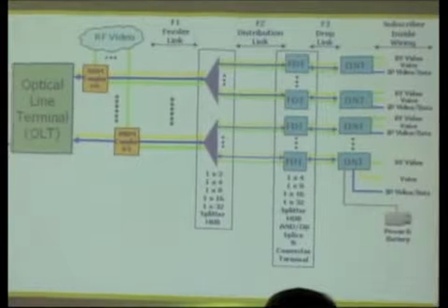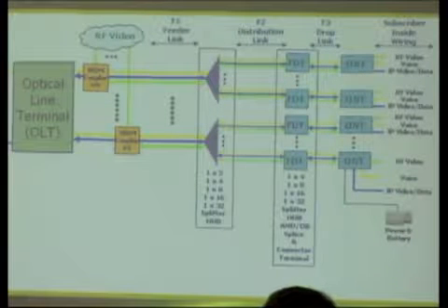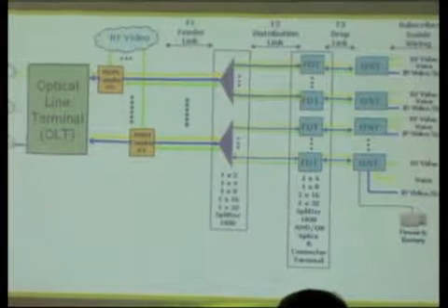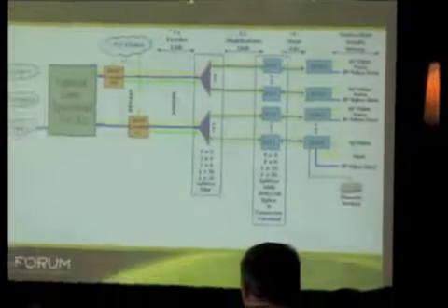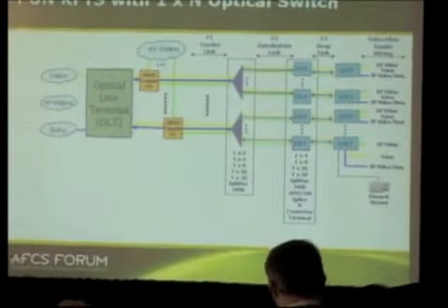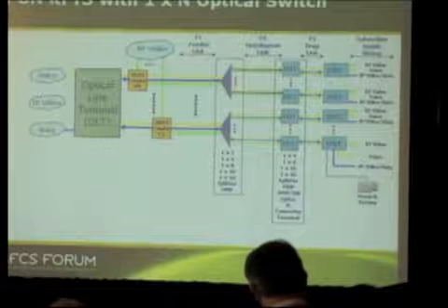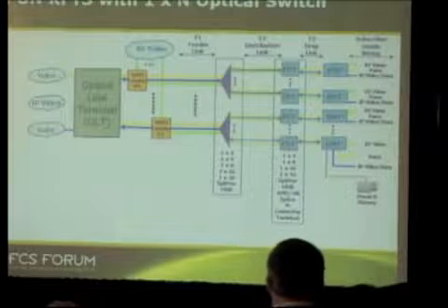As a matter of fact, that was Verizon's initial reason not to deploy multiple splitters. They said, how can we really do that? How can I get an OTDR look through that? Even more, how can I train a technician to figure out there's a problem when he looks at the OTDR? So that's another issue that occurs. But that's starting to occur even in Verizon, where they're putting a 1x2 in the central office.